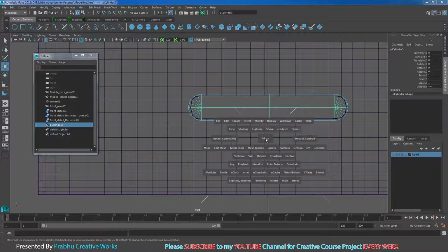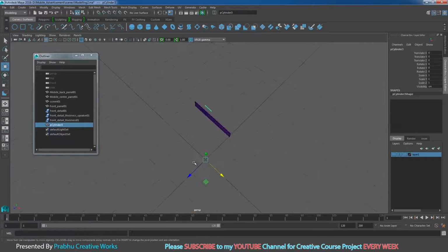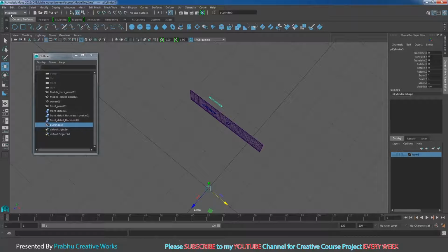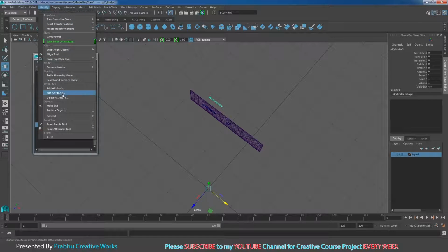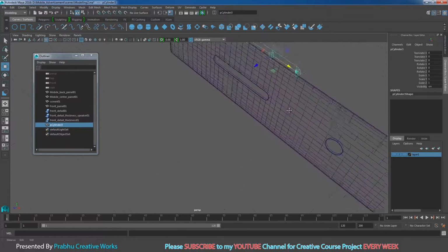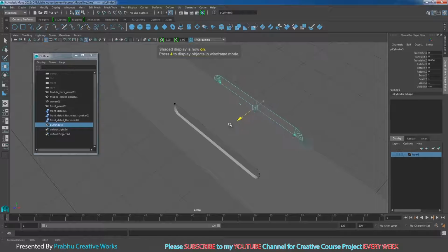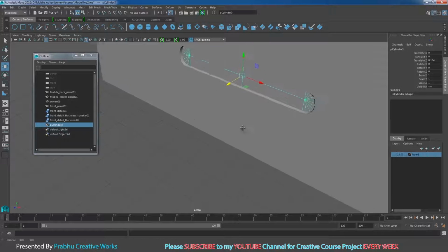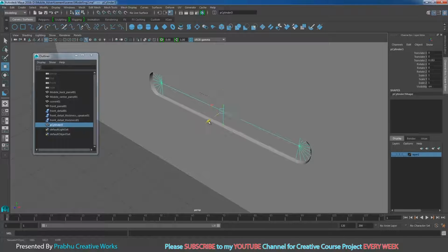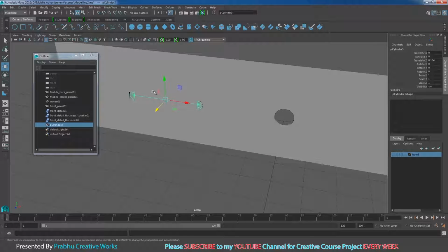So I want to go to perspective. See here, our pivot is in the center of the grid. So I want to change the pivot. So select the object, go to modify and choose center pivot. So I want to move, press 5 on the keyboard to see the shaded mode. So I want to move a little bit over here. So like this.